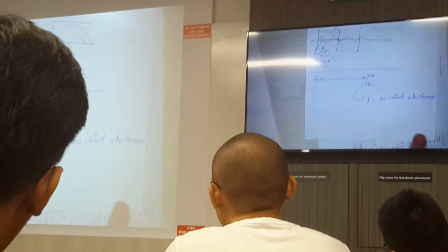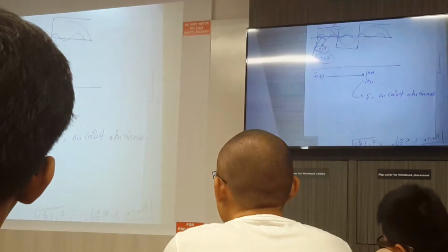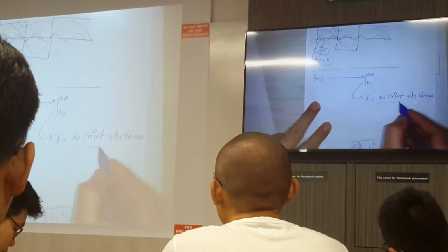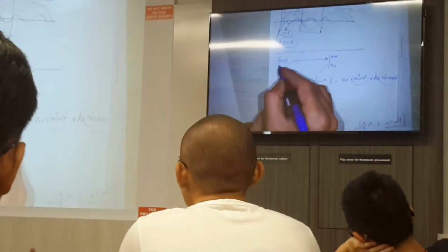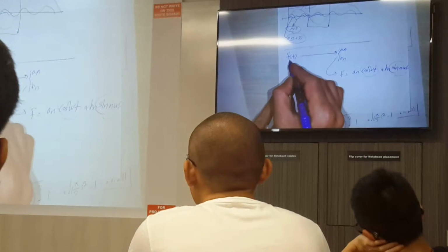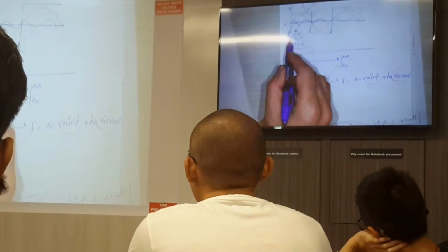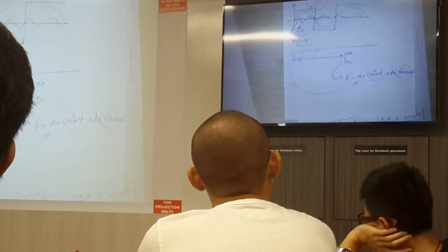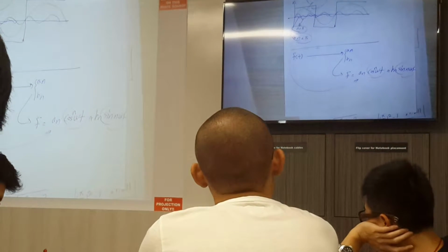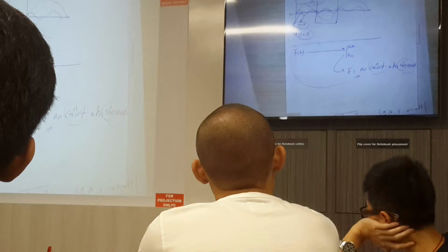So this is the Fourier transform of the signal which I have. You see here, this is the sine or cosine, the sinusoidal waveform which we know. So we are converting this signal, which was a square wave, to a signal consisting of 2, 3, 4 or n number of sinusoidal waveforms. So this is the purpose.